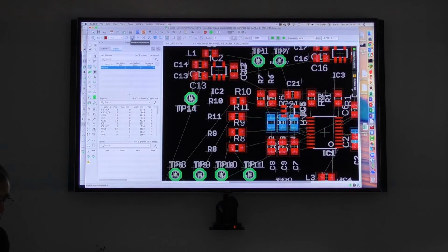We have an ignore obstacles, we have a walk around obstacles. The ignore obstacles is something where you have all the freedom to draw connections. If I would use this mode, click on it, I have to decide about the width of my trace. You know, we have 150 micrometers, which is pretty good, 6 mil, and it fits nearly. But if you look now and compare the size of the pad and the width of the trace, this doesn't fit together. The trace is too small.